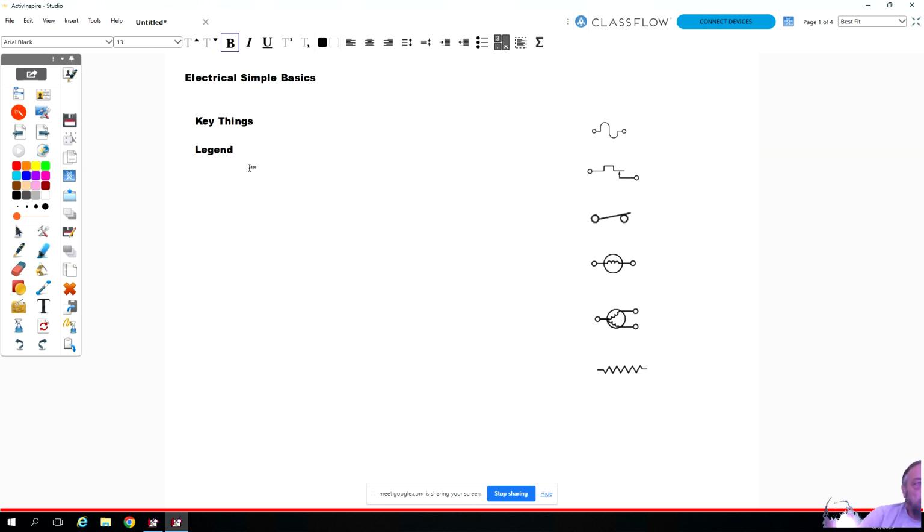but what about the actual diagram? When you look at a diagram, what are you looking for? We're looking for our wires. We're looking for our points of where our voltage, where our current's coming from. Is it going to be AC? Is it going to be DC? What's getting fed? Where's it going to? Okay, so our loads, things like that. So a couple of key things: voltages, loads, and the circuit path. Those are a lot of key things that we want to look for.